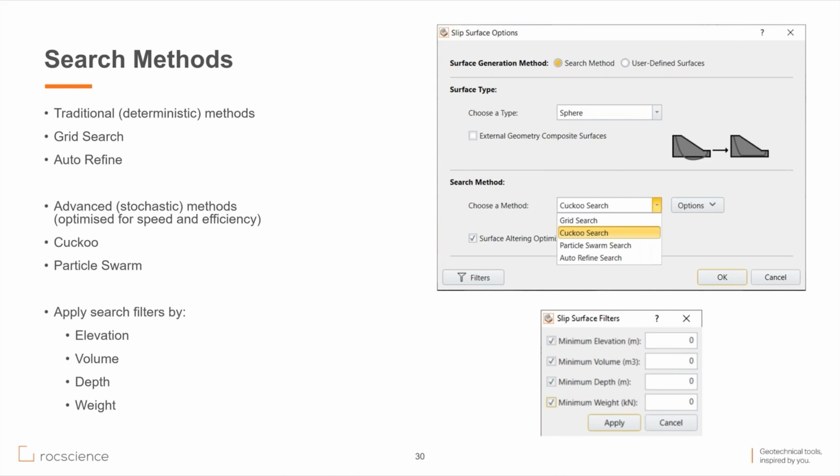For a wedge failure consisting of more than one weak plane, is it practical to include multiple planes of weak surfaces? There are multiple ways that you can model wedge failures within Slide3. Obviously, Rocscience has SWedge as well, where you can model up to 5 release planes.